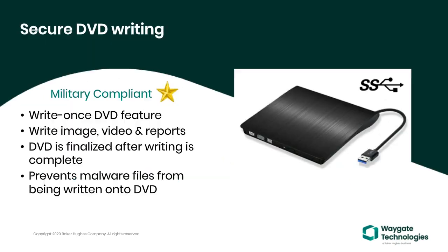In cases where USB thumb drives or other USB media types are not allowed due to cybersecurity policies, an external USB-attached DVD read-write drive may be used to export and import data to and from the Mentor Visual IQ. Note that once the MVIQ writes data to the DVD drive, the media is finalized so that no malware files may be included on that DVD at a later date.